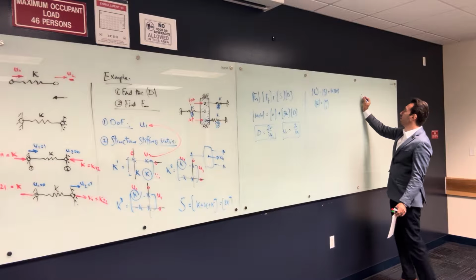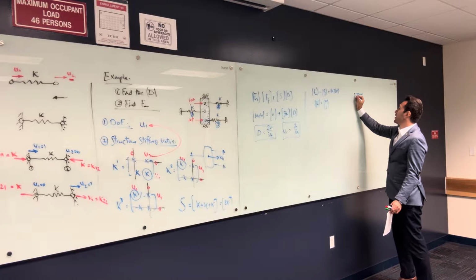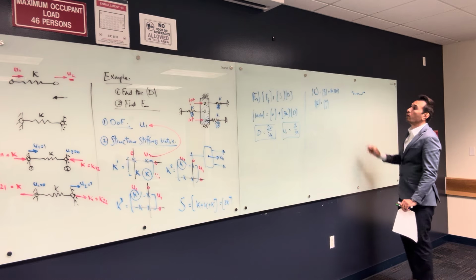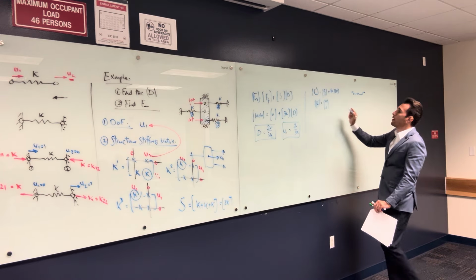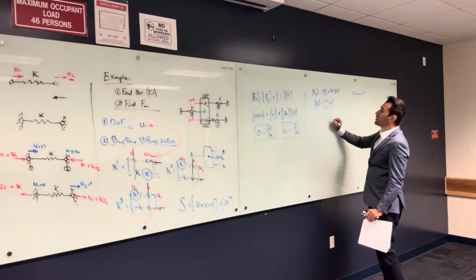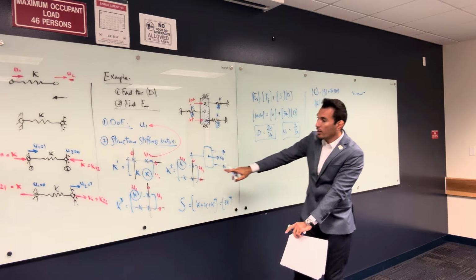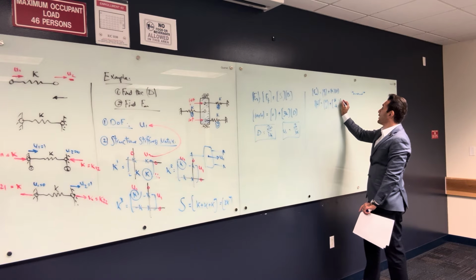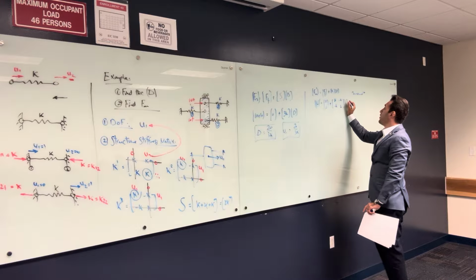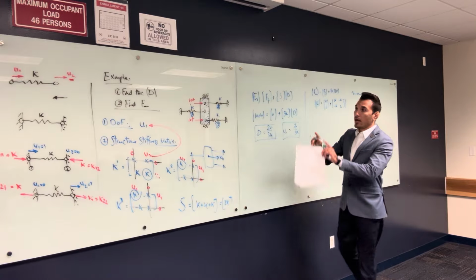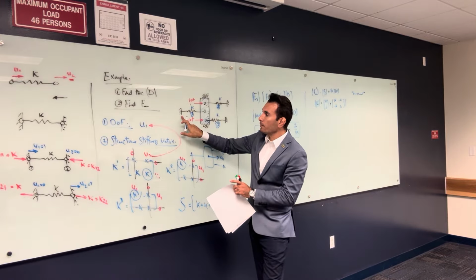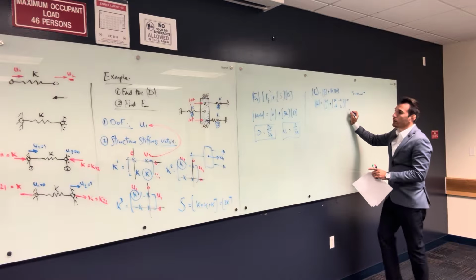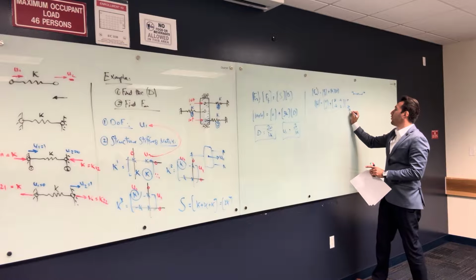What do the two zeros mean? The two zeros mean, if this is the spring, I'm looking for the force here and the force here. The two forces, number 1 and number 2. Plus the stiffness matrix of member number 1: K, negative K, negative K, K. Multiplied by the displacement at member number 1. What is the displacement here? 0. What is the displacement here? U1. So 0, and I have here 20 over 3K.